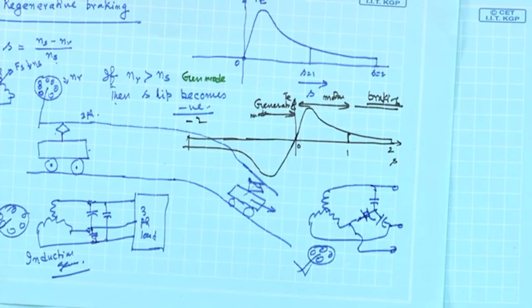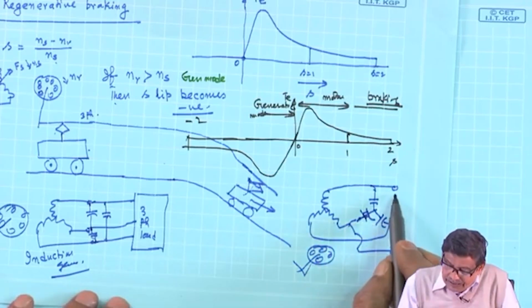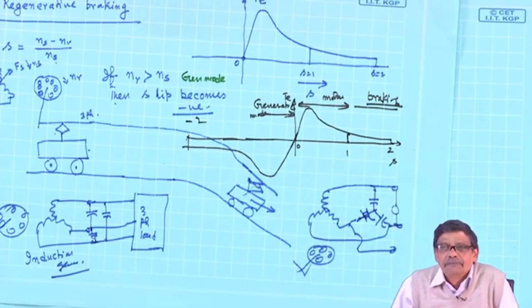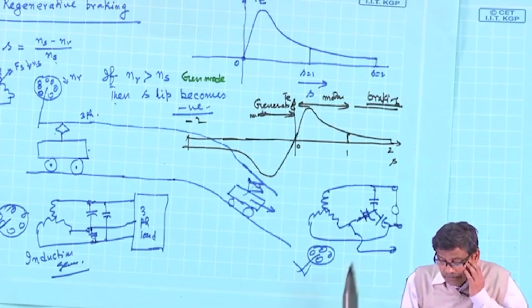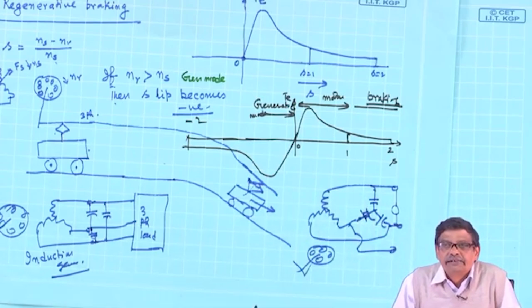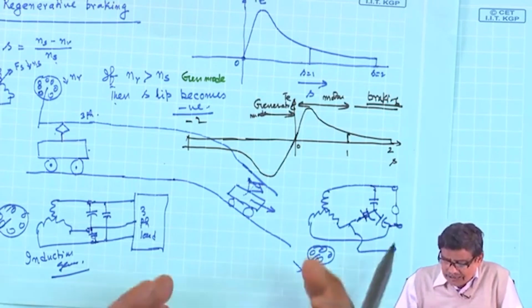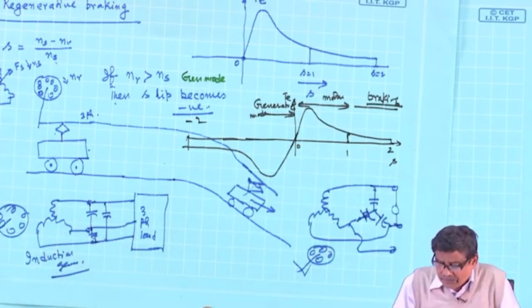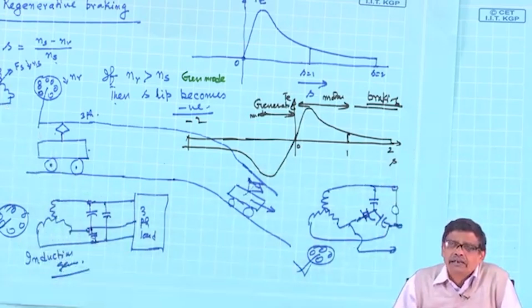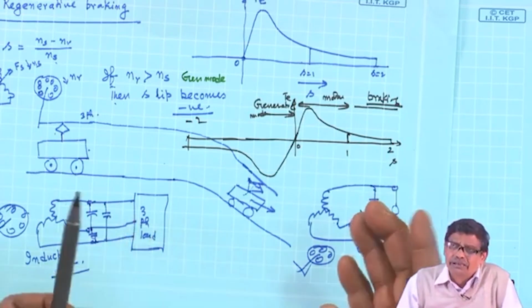Then I am telling the observation, no explanation. Then you will see that for some values of capacitance, a reasonable voltage has appeared here. Okay? Because these capacitors will provide that initial excitation of the coil. But anyway, this generator is not very good. The moment you load it, voltage drastically falls. If time permits, I will discuss about that.